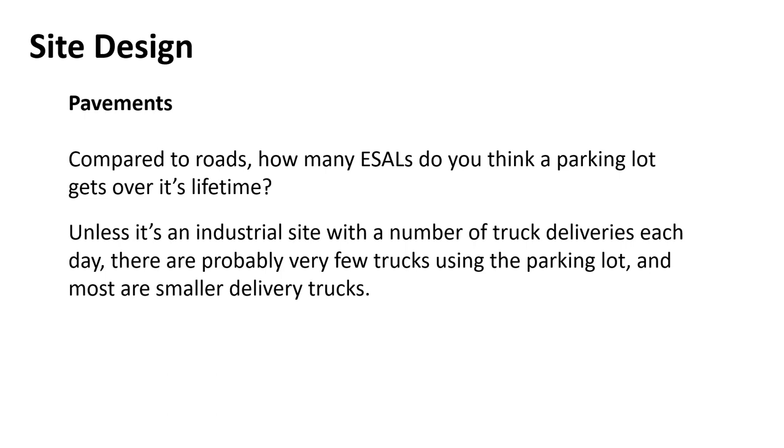In fact, we went through a project again like about a month ago. Their ESAL calculations and their structural number were so low, it was almost impossible to figure out a pavement for that. I think it required like 2 or 2.5 inches is all it would need based on strength of the pavement. And so we'll talk about that in a second. That's not what controls, right?